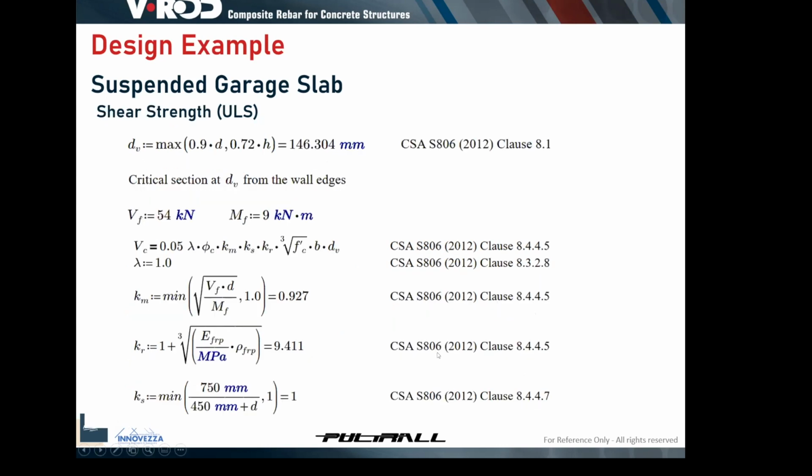Then the shear design. First, we calculated the dv, which is the shear depth. It's the maximum of 0.9 the depth or 0.72 of the height of the section. Then we calculated the shear forces from the finite element modeling.